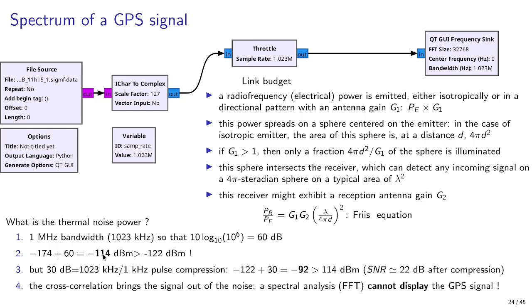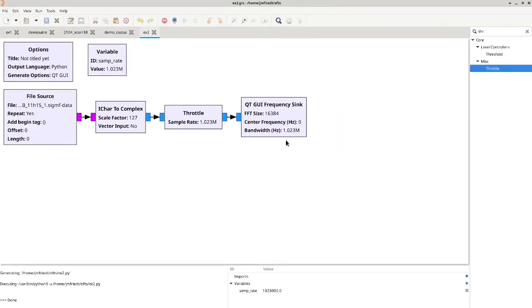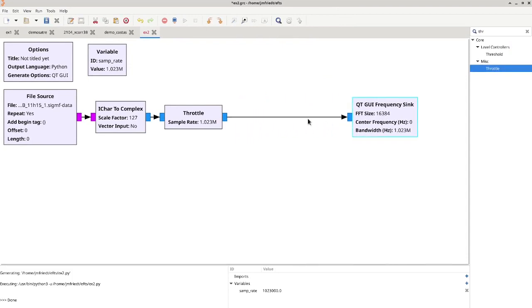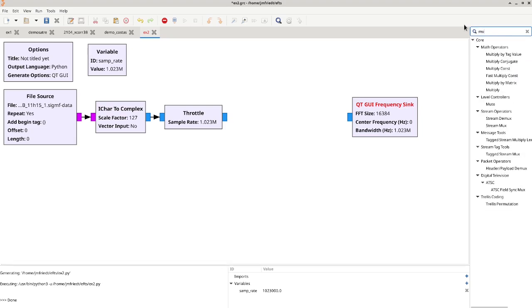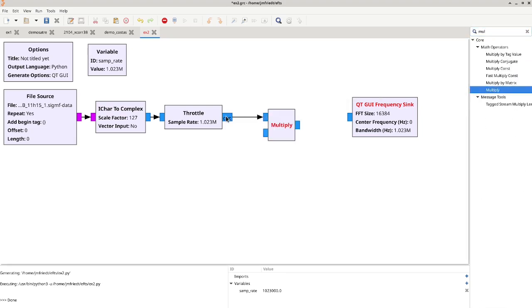However, we have seen that the spectrum spreading can be cancelled by squaring, and the despreading will lead to, for energy conservation, the accumulation of energy by a signal-to-noise ratio improvement equal to the number of bits, namely, in the case of a 1000-bit long sequence, 30 dB.